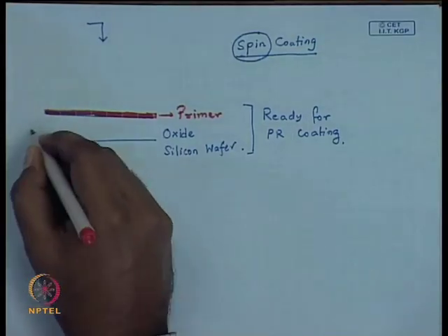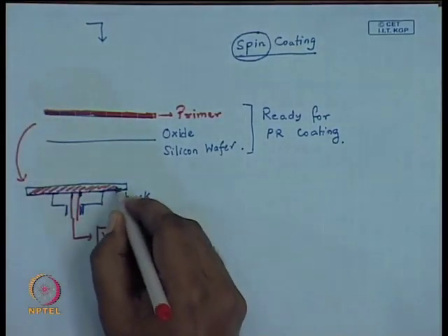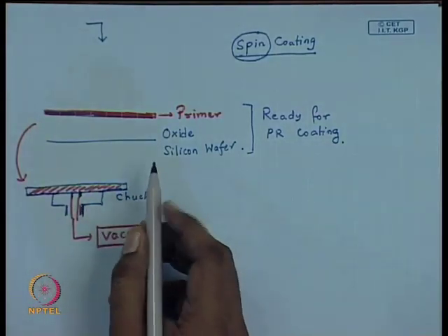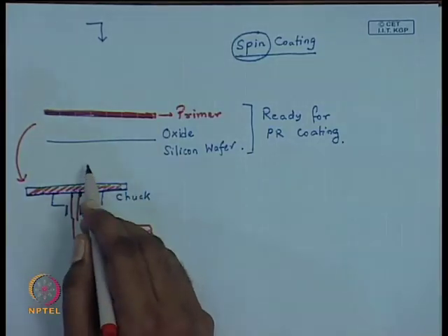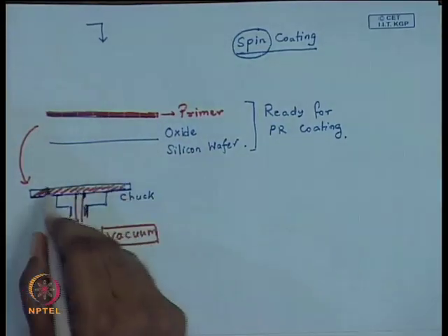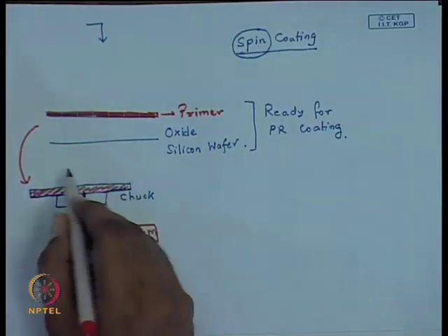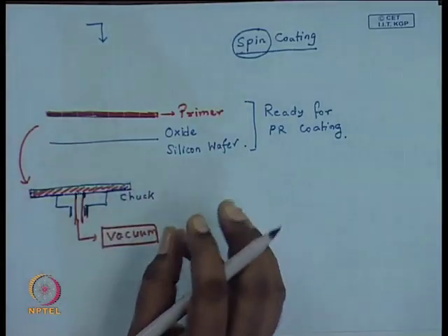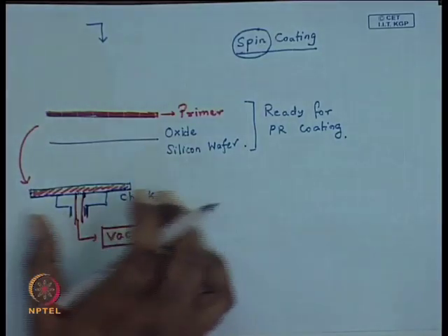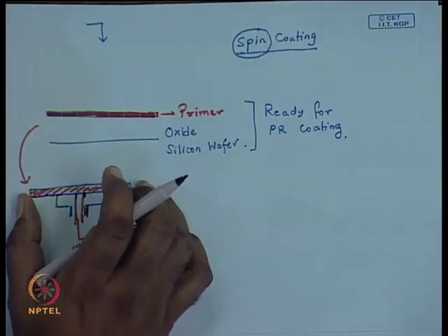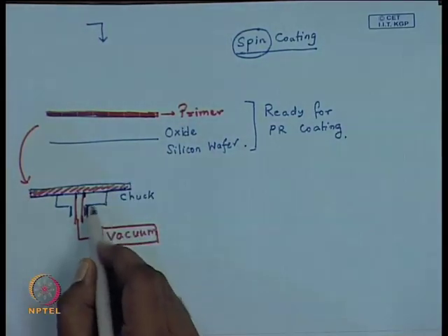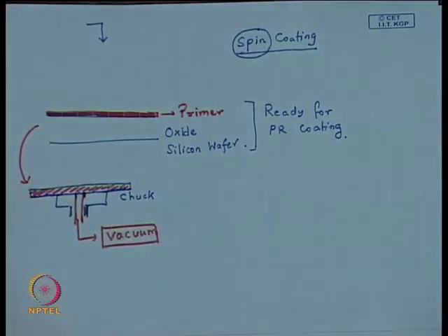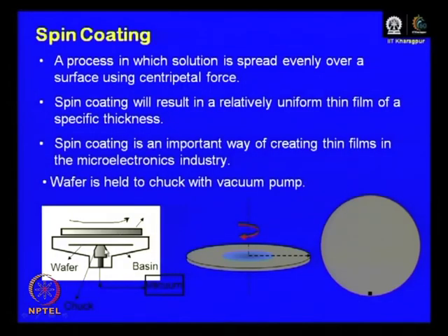So, this is that primed wafer which you place on the chuck and which is now ready for spin coating. The rotation starts after you apply a solution of the photoresist layer, or dispense the photoresist solution, on this wafer. Before that we were talking about the mechanism by which this substrate, in this case the silicon wafer, is held to the chuck, and typically that is achieved by a vacuum connection. Here you can see that also in this transparency.